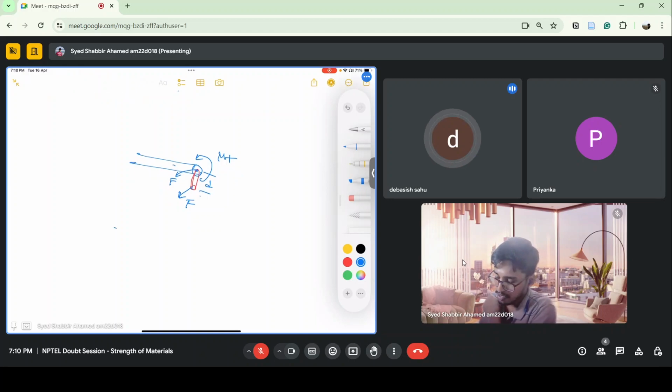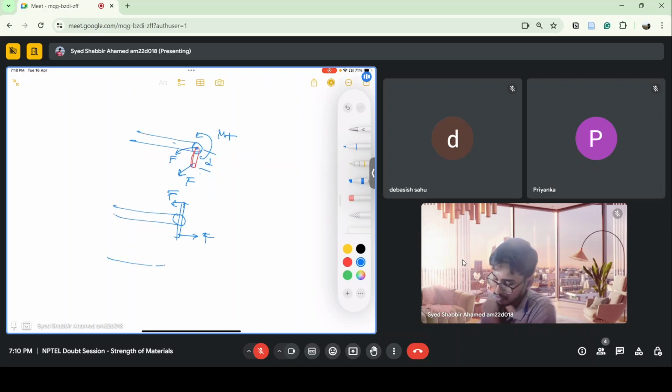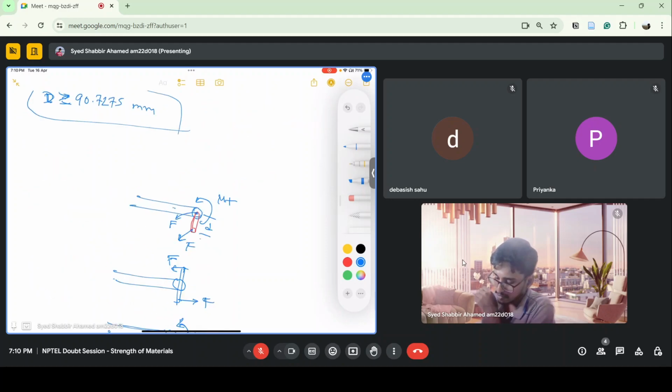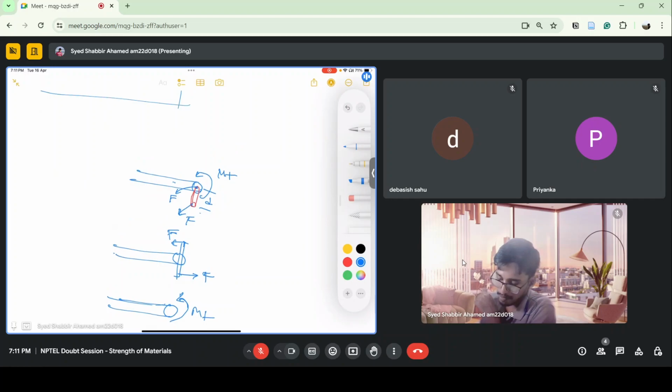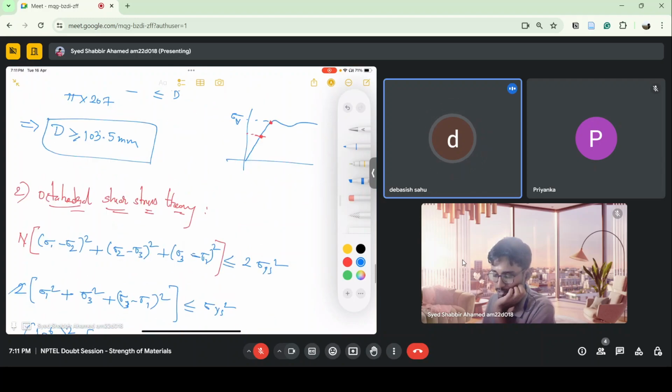So let's say if I had a shaft like this, and I am applying force like this. Basically, I am applying a couple. Then I will get only torsion moment because I have shifted these two forces. I will get net force 0 here. So I'll get only the torsion moment. So this will not have any bending effect, but this will have a bending effect.